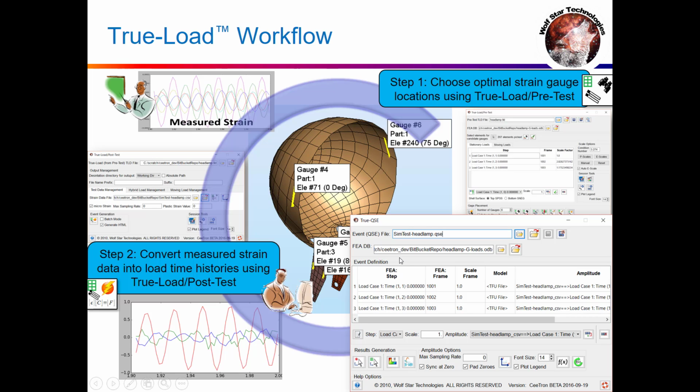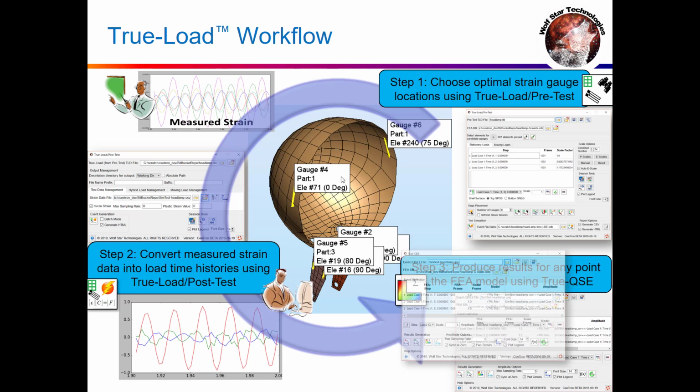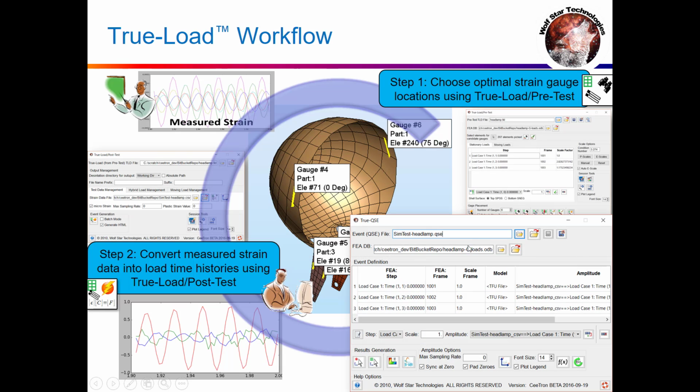Now, the whole point of TrueLoad is to understand the loads and then do redesign. So we can go back to our FEA model and change it. We can poke holes in it, we can thicken things up, we can do whatever we like. The requirement with TrueLoad is that you only solve your FEA model for the first 3-unit load cases. Then we just come back to QSE, and have QSE point to your new set of FEA results. And that's all we do.